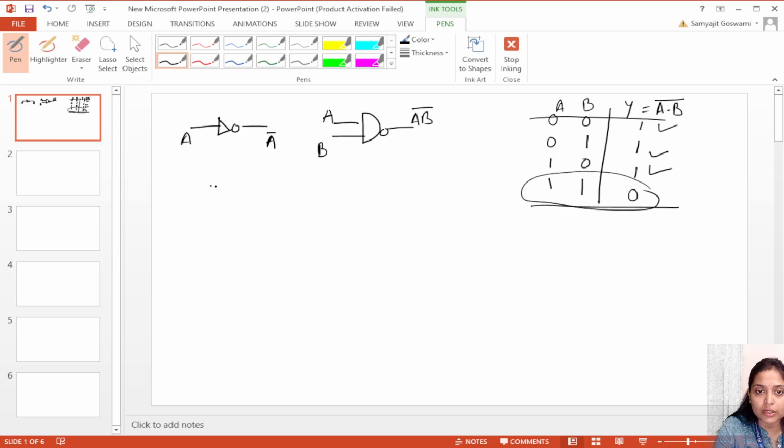So now if I consider this NAND gate, both the inputs are A. I can write this diagram in this way also. So both as A, I can short both the inputs and then give A. So here also the same thing happens. In both the inputs A is going. So I have already said it will come A bar.